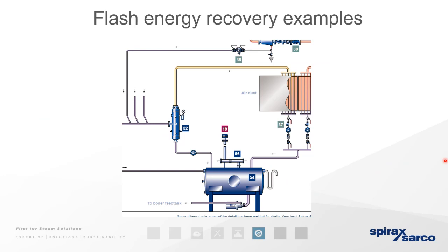And the resulting condensate at a low pressure and temperature can then also enter the condensate recovery unit and therefore be recovered back to the feed tank. So any flash that comes from a higher pressure, we can utilize a certain amount of that, where it would have gone to waste if it was just supplied to the condensate recovery unit by normal means.